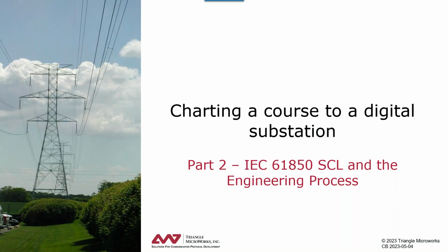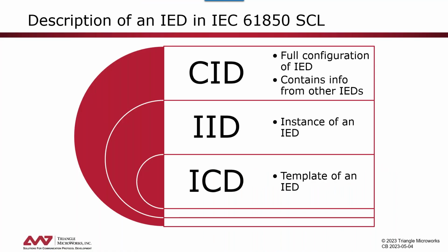Okay, so in the first part of this webinar series, we compared IEC 61850 with DNP3, and we explained some of the concepts of IEC 61850 related to communication and to modeling of application data. As part of that, we also compared the DNP3 XML file with the IED related files of the IEC 61850 system configuration language, or shortly called SCL. The files are used as part of the engineering process described in IEC 61850-6.